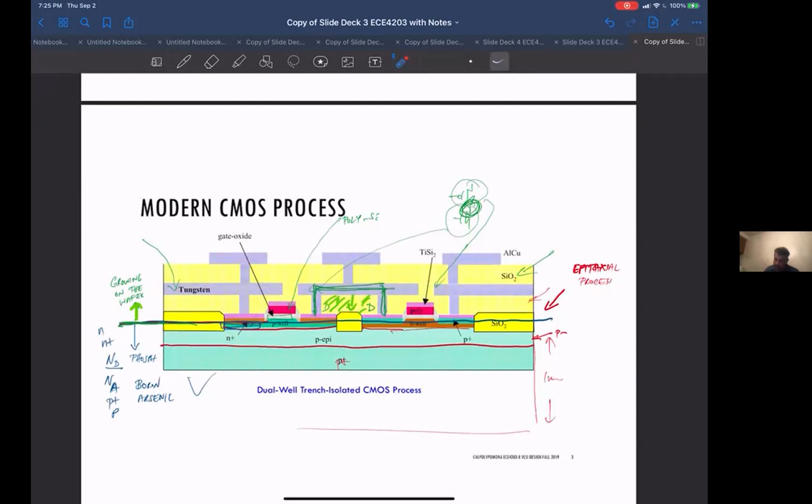In this particular case, the drawing doesn't really show it, because this is a short between this metal layer and this metal layer through here. But sometimes you want to have a metal layer up here that's not connected to the metal layer here. So you can't have it just sitting on top. You need alternating layers of metal, oxide, metal, oxide, with via connections between them where you draw them to get connectivity.